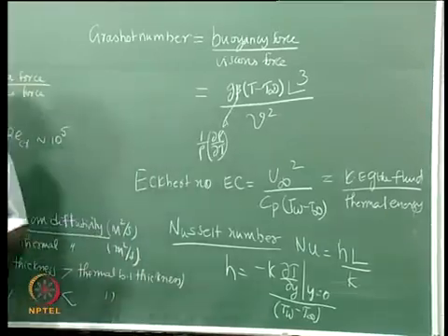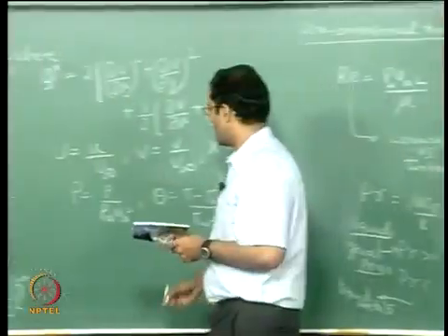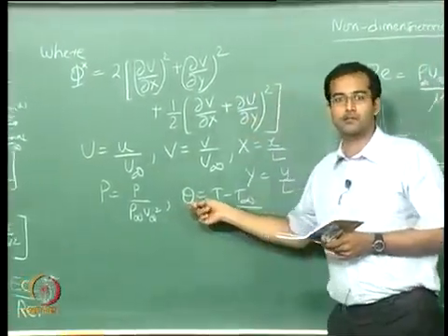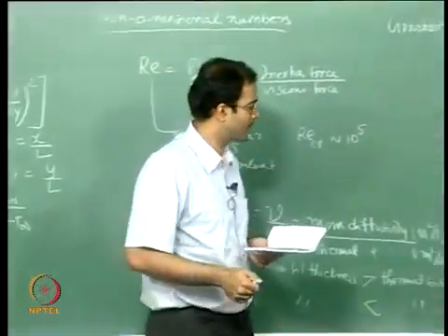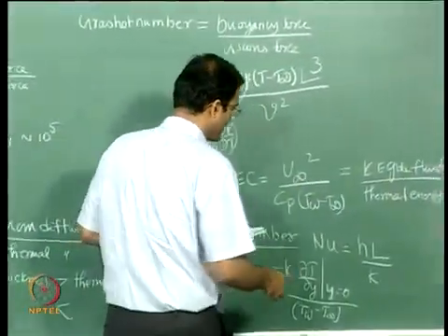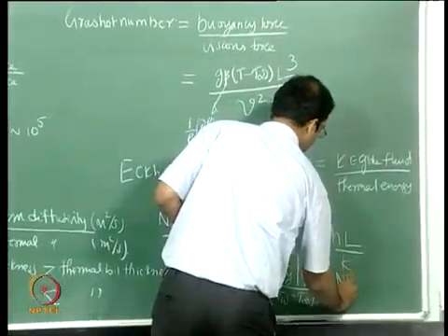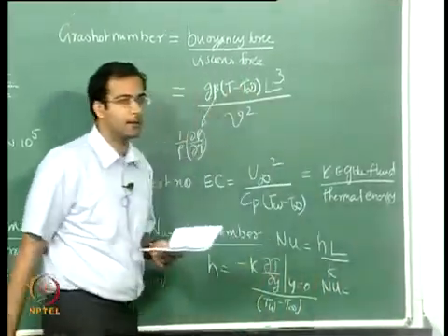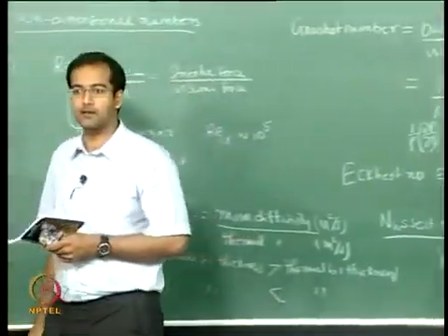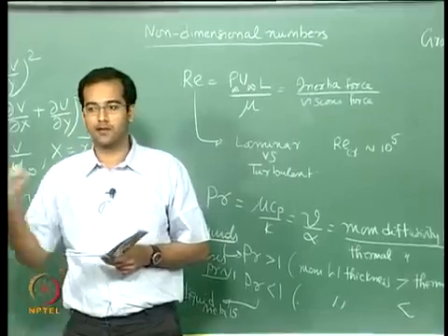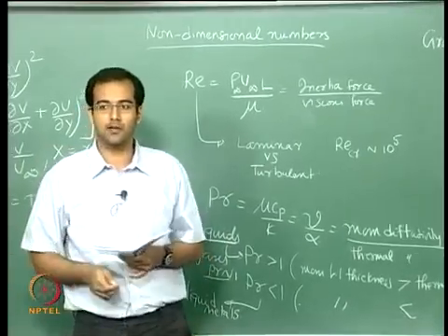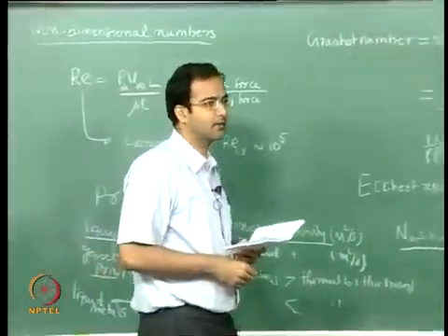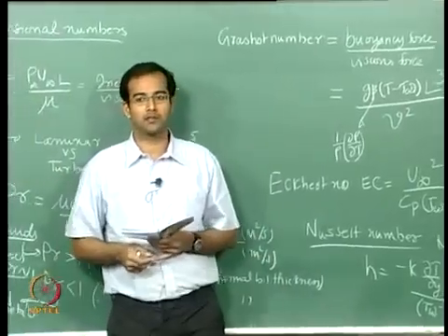Now if you use the non-dimensional temperature based on this definition, can you tell me what the Nusselt number will be in terms of the non-dimensional temperature gradient? You can plug the non-dimensional form into the dimensional form, and then calculate your Nusselt number in terms of the non-dimensional temperature gradient.